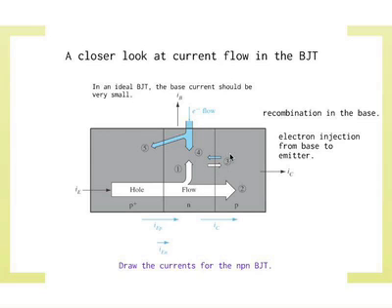The electrons extracted from the p-type to the n-type, the minority carriers extraction, and the holes going from the n-type to the p-type. Again, minority carrier extraction. Very small current, almost zero. Of course, when you add this side to the p-n junction, which is hole injection in this particular case, the situation changes. Now you have a way to control that reverse saturation current.